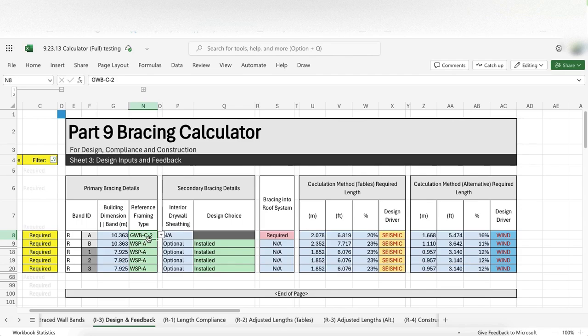However, when we double up the panel, in my mind, we are essentially doubling or increasing the amount of resisting force that we are providing in a panel per lineal foot or per lineal dimension.